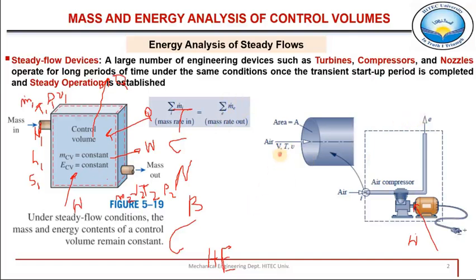And this mass, using one-dimensional approximation, we can calculate, because actually the velocity is not the same across this cross section. For example, this has been projected here to show this pipe through which fluid is entering into this control volume, and we know actually the velocity profile would look like this one. Right, velocity near the walls is near to 0, and then it is increasing, and highest at the center of this duct. So lowest velocity magnitude is at the walls.